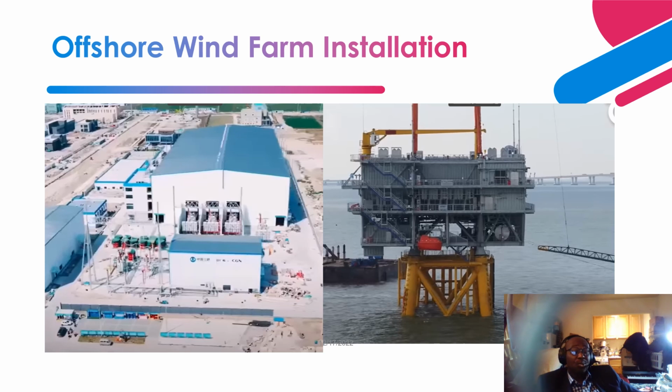He can choose to opt for gas insulated substations if he wants lower maintenance cost and higher reliability and a lower footprint. On the other hand, he can choose to go with an air insulated substation if, let's say, he doesn't care much about maintenance, because with air insulated substations you are exposed to the elements, right?